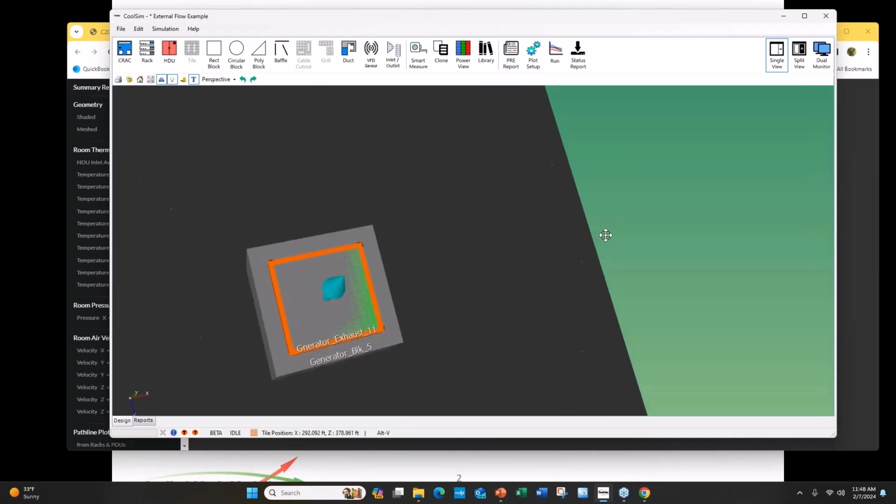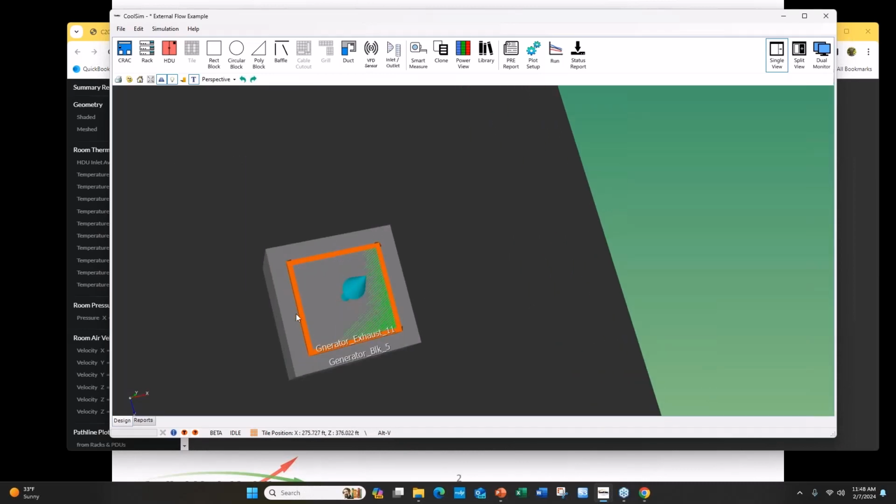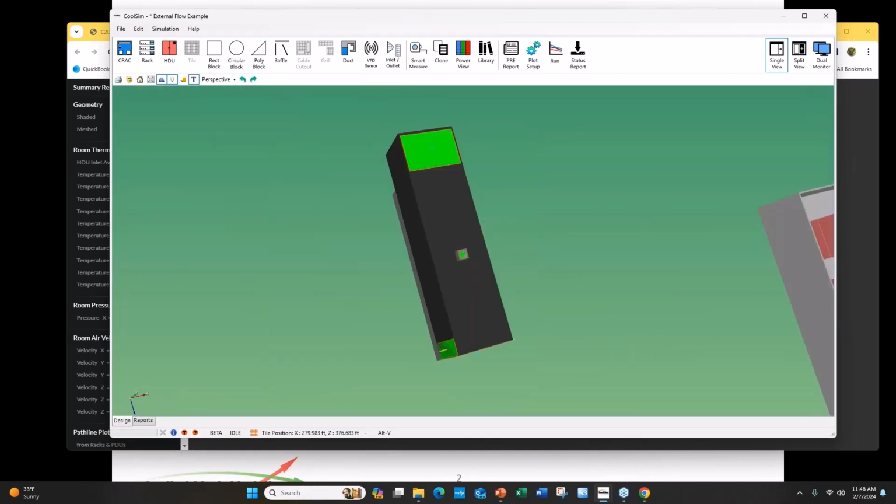Here you see how the inlet, in this case outlet, is not quite the size of the block. You should make it the same size as the block so the mesh doesn't have to do a double mesh here. You're already meshing this surface, but you'd also need to mesh this surface independently, and that's a very small geometry for a room of this size.